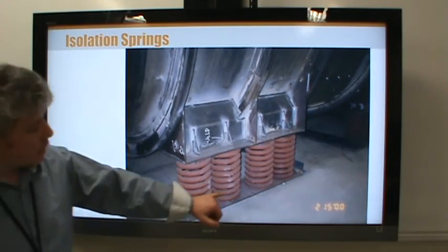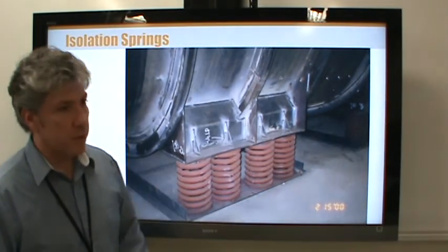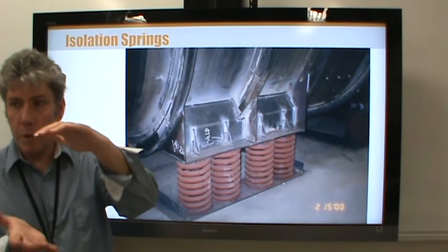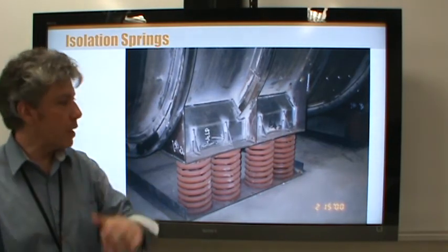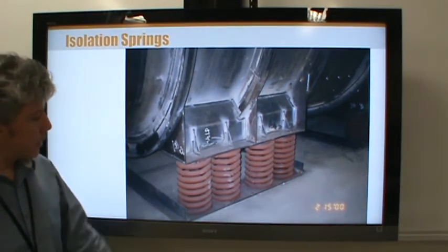So you might realize the end treatment makes a difference, because the end is what helps support the spring and prevent it from buckling out of the axial line.